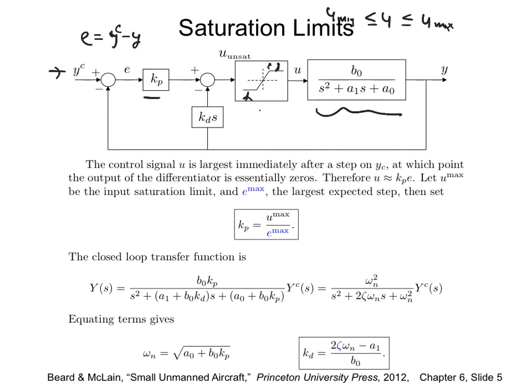We will not use Ki unless we find a steady state error. And it is also not desirable to put it in the inner loop; even if there is a steady state error in the inner loop, it's okay. For example, it's all right if I command 45 degrees of roll angle and I only get 40 degrees, or always 2 degrees less, because the objective is the heading change. So we will apply the integral control on the outer loop because that is more important. Go to 30 degrees north. That has to be exact. You cannot do a compromise there. But the roll angle plus minus 2 degrees, 3 degrees, we can handle that steady state error